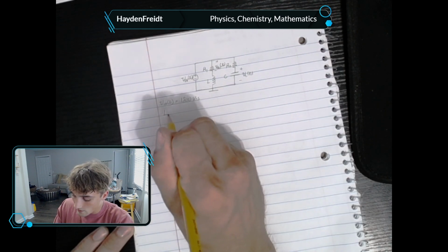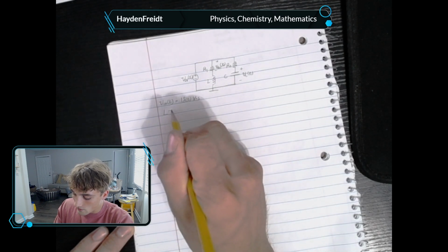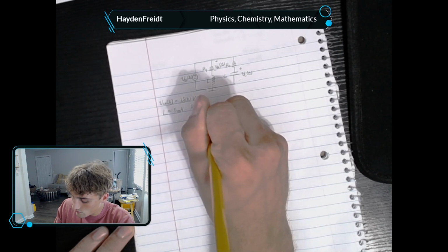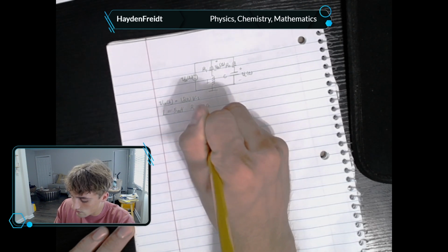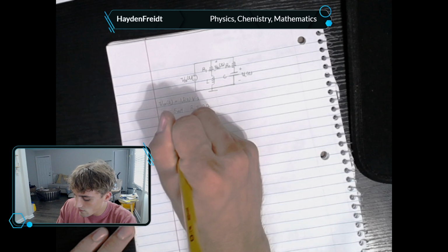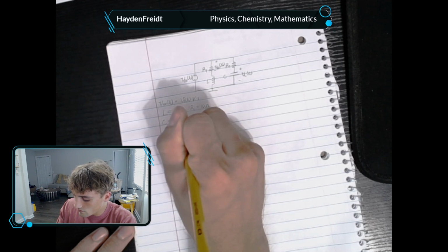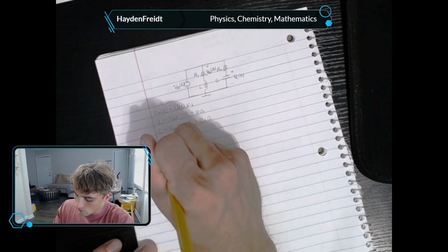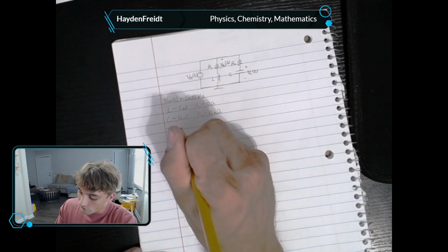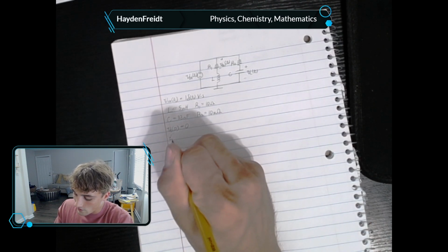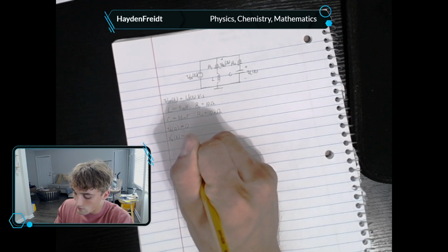L is the inductance of our inductor right here. L equals 5 millihenry. R1 equals 10 ohms. R2 equals 10 kilohms. C equals 33 nanofarads. That's our capacitance. Since the circuit is driven by an impulse and there is no other source of energy, the capacitor voltage and inductor current at t equals 0 will be 0. But we're also going to define that. So Vc of 0, once the impulse happens, equals 0. And then IL, the current through our inductor at time 0, also equals 0.